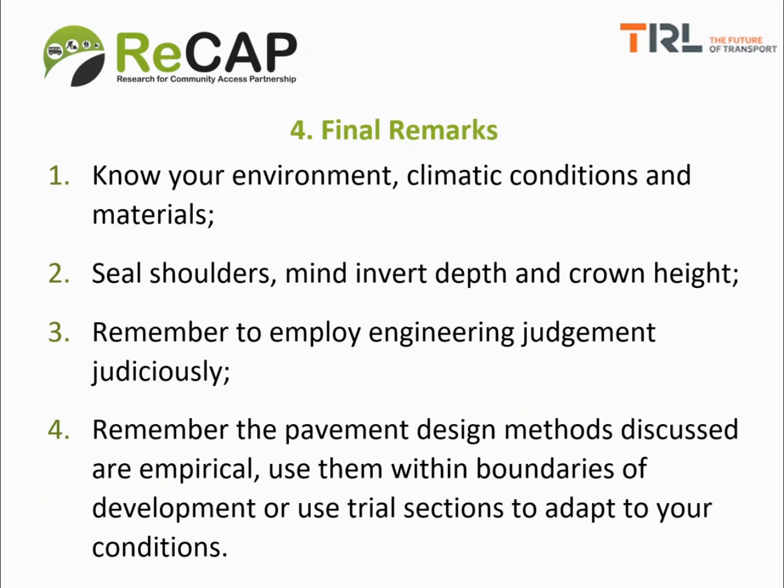The first remark is that you should know your environment, the climatic conditions, and the materials, because the design methods, as you remember, are mostly empirical, and you'll find that some local knowledge of the performance of your materials from roads that have been in service will go a long way. You may find that the characteristics of these materials may not agree with some of the specifications that have been developed for low volume roads, but they are working well.